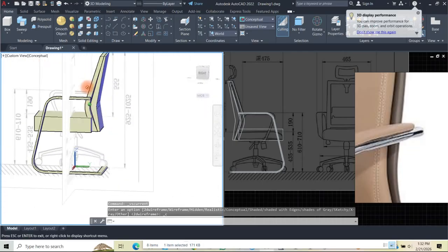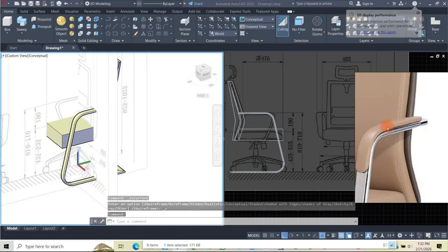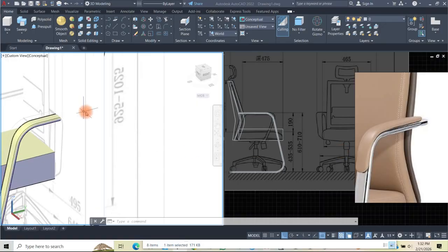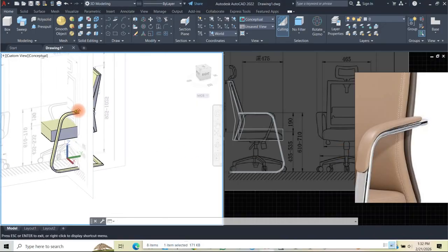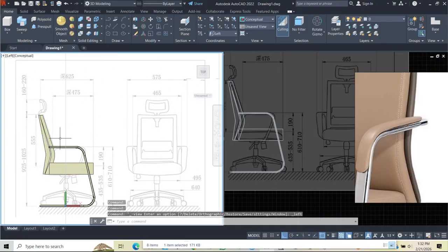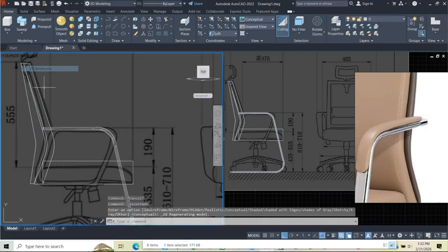Okay, so that's perfect. So the only other thing left is this. I also want to create this shape and sweep this as well. Alright, so we can also do the line and create this profile, and then we can sweep along this. So let's quickly do that. We can go to the left side. It doesn't really matter. So left side, change this to 2D wireframe.